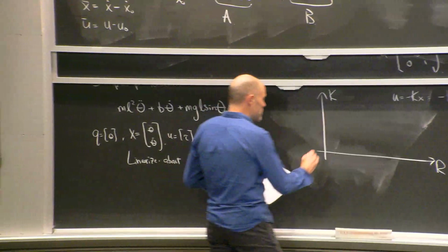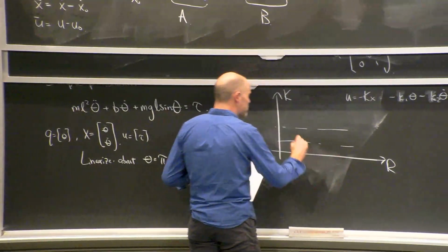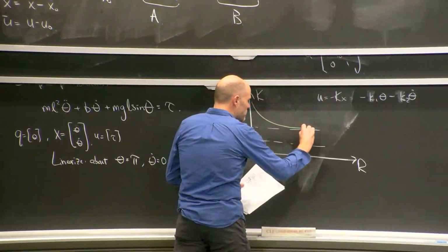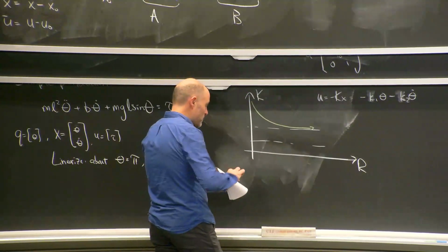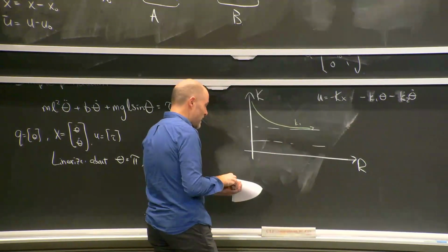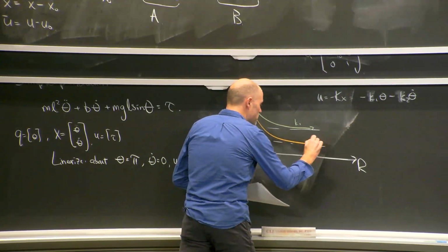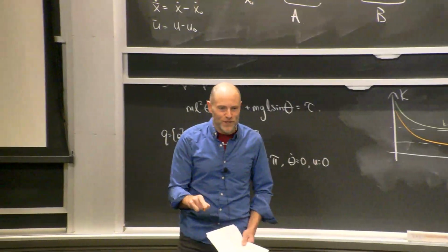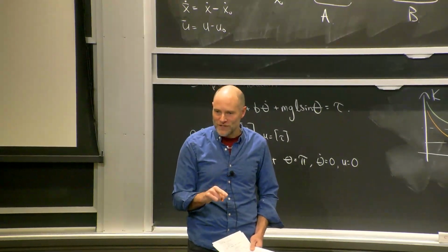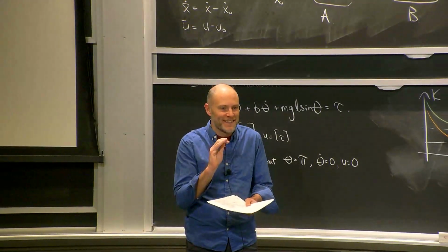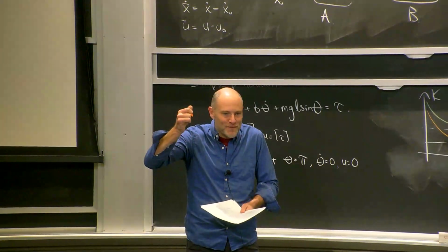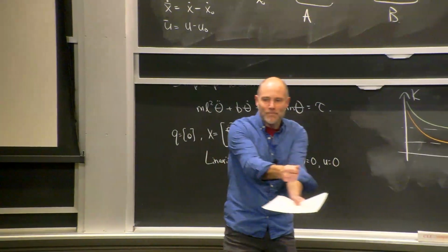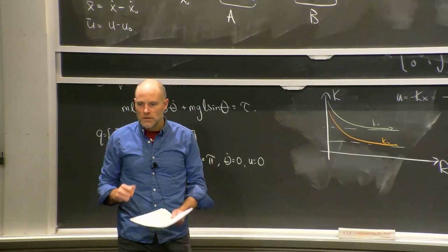Okay, so what happens is K1 sort of goes down and asymptotes, and this is K1, and K2 goes down and asymptotes on another thing. It won't let you go to 0. It has to return stabilizing controllers. It's like guardrails that are saying, you can put in any Q and R, you can ask me to do like, I hate spending any energy, okay, and it'll still stop you from making an unstable controller. It's a very elegant way.